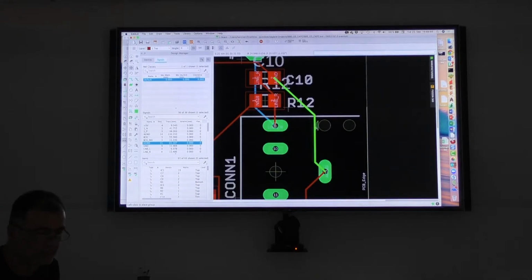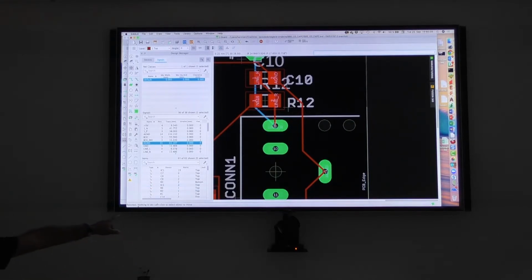That's also something new. The move, we keep the angles persistent. We try to have the angles in 90 or 45 degrees. So I change this. I do a save. I run the DRC again to check if there are any other problems. It says no errors. I could also do the ratsnest command again. And that's the message I want to see. Nothing to do. So if ratsnest says nothing to do, everything is routed, we can hope that the board will work when we get it back.